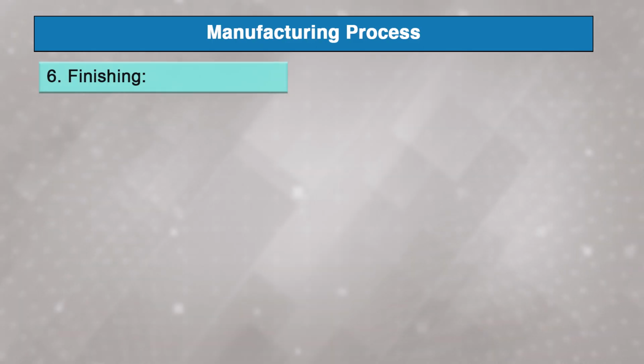Inadequate curing can result in weaker concrete which may not meet the design specification. In some cases, accelerated curing methods such as steam curing may be used to speed up the process, allowing for faster production times. And next step is the finishing.